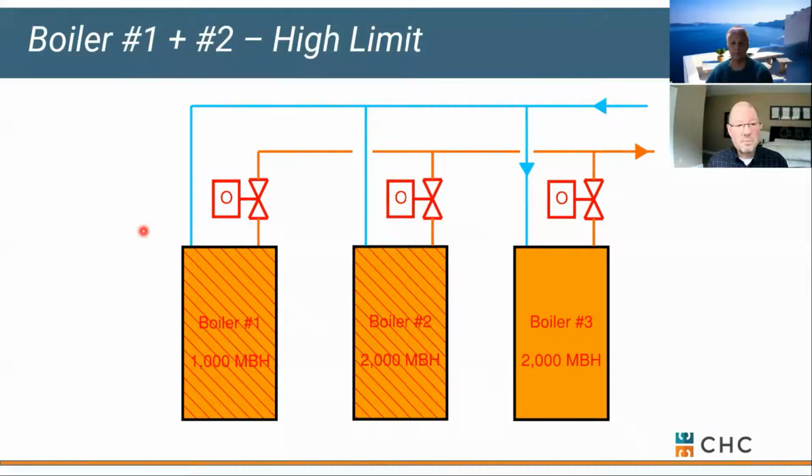Decouple the boiler system and replace motorized valves with pumps, basically turning it into primary secondary. Decoupling would simply mean we'd add some closely spaced T's here and a common pipe and replace these motorized valves with dedicated pumps. That way, every time the boiler was to fire, we would get dedicated flow through it because we have a pump that would kick on. To me, that's the best solution, but all these are problematic after the fact.